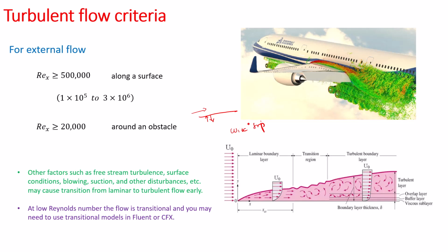And that is to be done because we want to compare our experimental data with the CFD, which is fully turbulent, like the SST or K omega models or K epsilon model, because they are fully turbulent flows. So in order to compare the results of the turbulence model or validate the CFD code, we forcefully make the flow turbulent so that we can compare them easily.